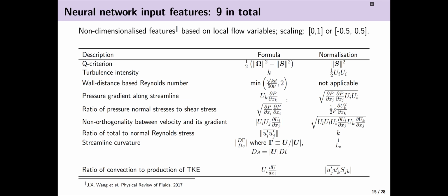So the eigenspace perturbation is available in SU2, which is open source. I do the eigenspace perturbation simulations in SU2 using the same mesh and the same setup. We're assuming that SU2 and OpenFOAM will be very similar, so we're neglecting any differences between the two models in the two different software suites. Then I compute the variance, and when I'm doing data assimilation, I'm doing it in DAFoam.